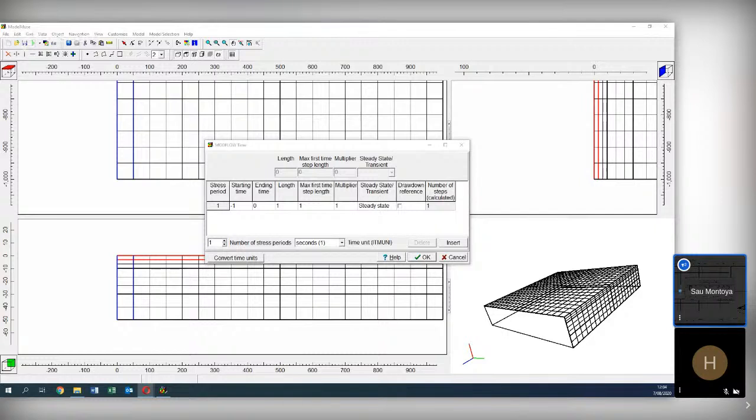In groundwater, the literature and some books say you have aquiclude, aquitard, aquifers, and some others. However, in ModFlow, a transmissive aquifer is expressed as high K, an aquitard will be expressed as low K, and semi-confined will be intermediate low K. Everything in groundwater modeling is related to the K value, and this is something you have to take into account.